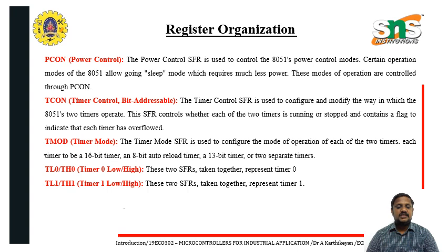Each timer can work as a 16-bit timer, an 8-bit auto-reload timer, or a 13-bit timer. TL0 and TH0, timer low and high, are the SFRs that represent timer 0, and TL1 and TH1 are the low and high bytes that represent timer 1.